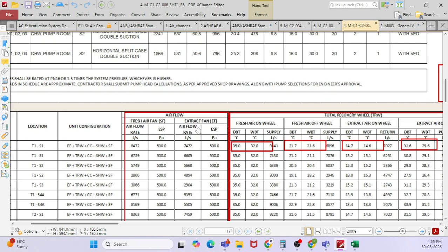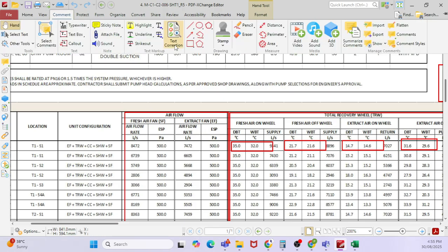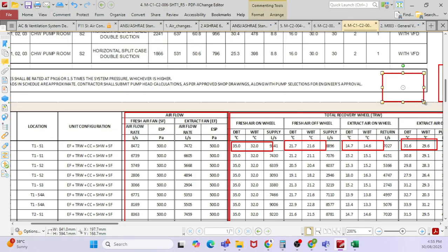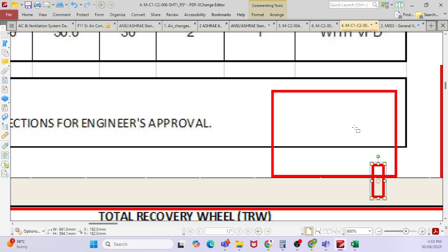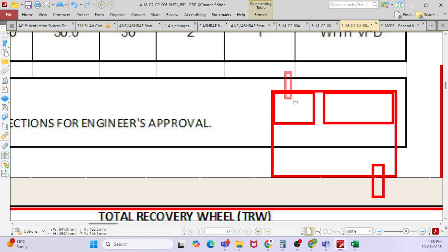But for this one, engineer, which specific area do we need to maintain neutral pressure? See, just now I told you. Say you have one space, and you are going to provide fresh air, and then you have a toilet here and a pantry here. So here you are going to create positive pressure. How? Because you are pumping the air into this particular space and you are not taking any exhaust here, so this air will be positive. And when you take the air from here you will always take exhaust, right? Yes. So here you will create negative pressure.